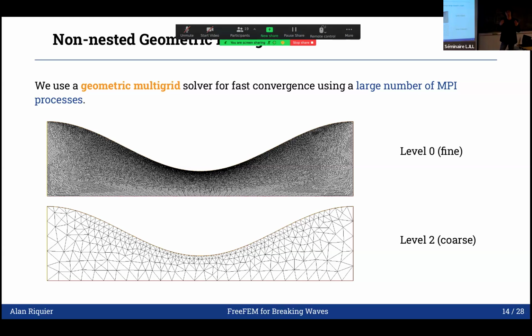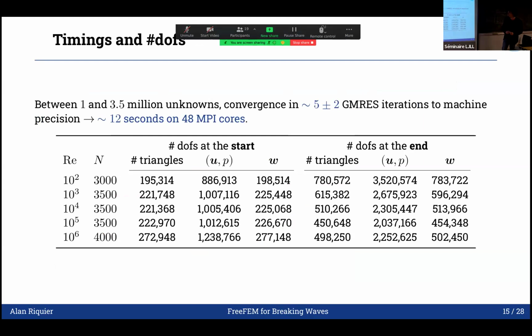that if I increase the number of subdomains, the information from domain to domain will take time to travel. So by using this kind of preconditioner, we increase the speed of transmission of the information from domain to domain, so that the number of iterations it takes to converge to the solution remains somewhat constant while increasing the number of subdomains. When doing so, here is some of the timing I had.